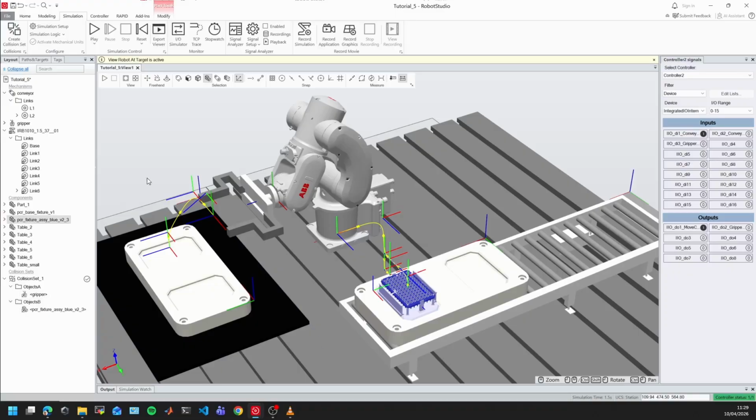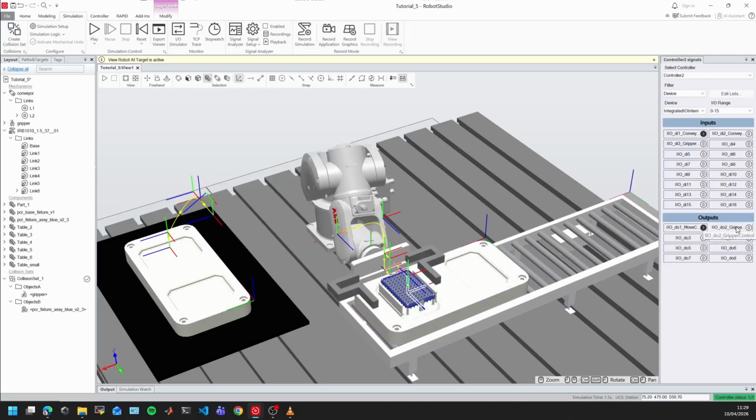There you go, and you can see that it's actually going to check the collision. Look, I'm going to move the robot there and close the gripper, and you can see the collision. So that collision can trigger an event or something. I can use collisions not only to verify things, because normally collisions are used to verify that the object is in a correct position, whatever.